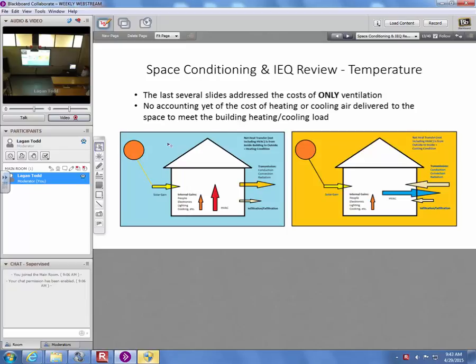So you'll remember that these are from previous lecture. When it's cold outside, we've got some heat coming in from solar gain. We've got heat that's leaving through conduction and convection and basically our transmission losses. Okay, we've got infiltration losses or exfiltration losses, either way.